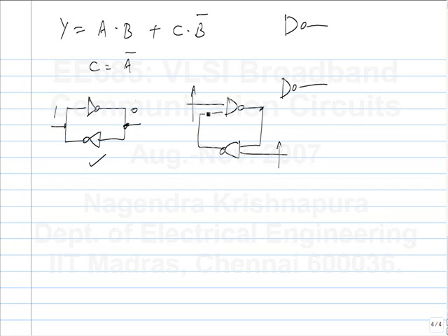So we need positive feedback. How do we do that with our current mode logic gates? How do we implement this? The MUX has a feedback from output to input. Don't we have to do this? We need 2 inverters to put in feedback. This is what we normally do. Why do we do this?